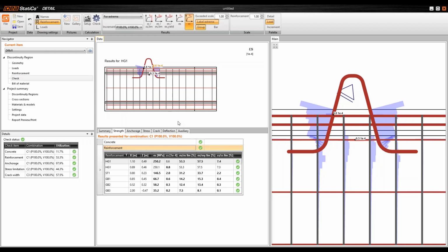Okay, and then we had also one question regarding the Beam application, so maybe I'll try to answer that. There was a question whether we check the indirectly supported beam when we include the reactions as a load, I mean the vertical forces and the torsional moments. We must confess that Article 9.2.5 is not checked at the moment.